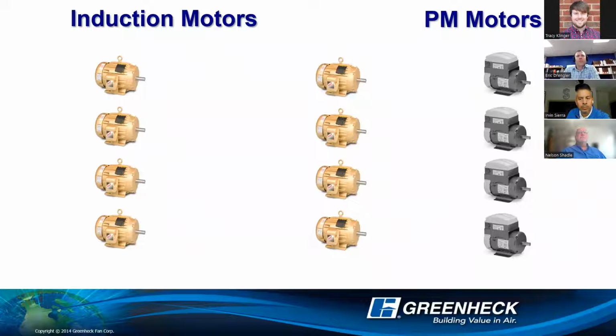Now, when it comes to different motor technologies, whether it's induction motors where you need a VFD, or permanent magnet motor or EC motor, I use those terms interchangeably, but one can assume that there's a drive included with that particular motor. There's different ways to wire these things. With induction motors, the old school way is just to have individual VFDs for each induction motor. So you send power and a control signal to each VFD, and then each motor has its own VFD.